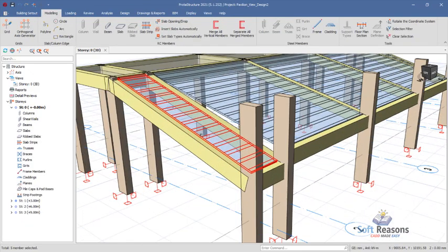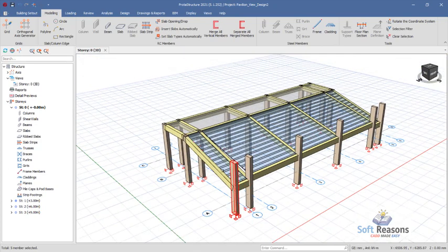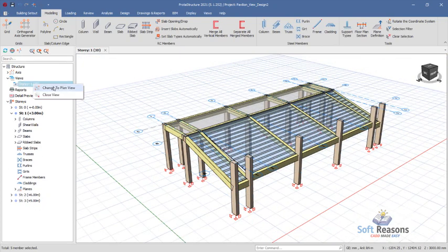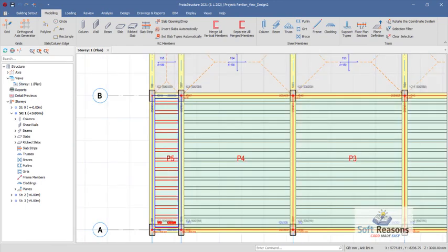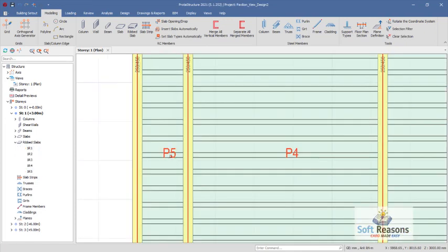so we need to make the entrance staircase more sloped than this. So what we need to do, you navigate to story 1 right there, get to the plan view of story 1, and then you pick this plane P5. You make sure this plane is rightly selected.